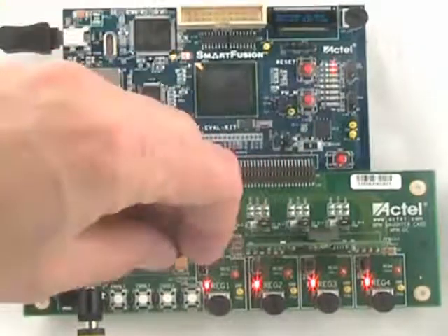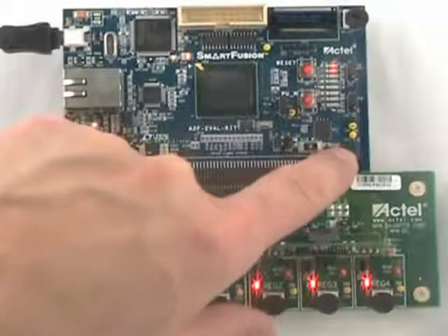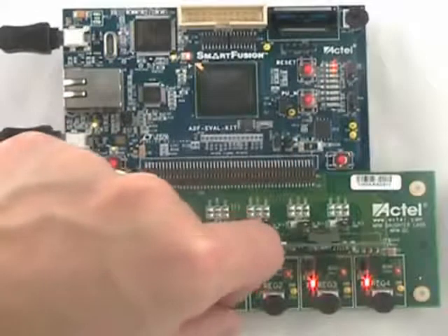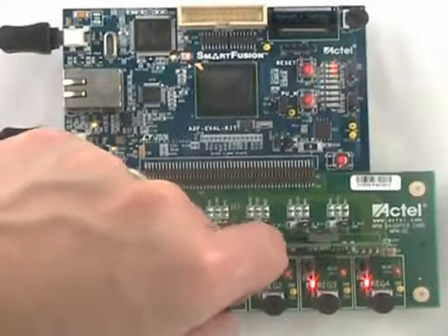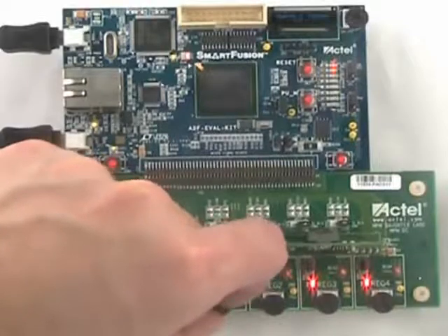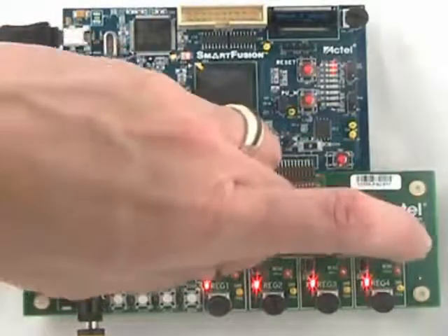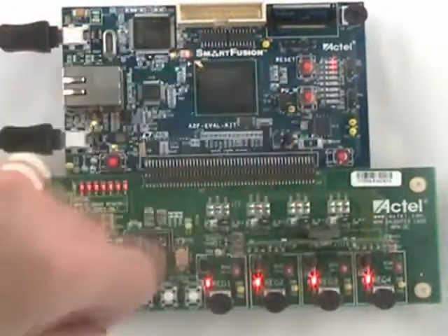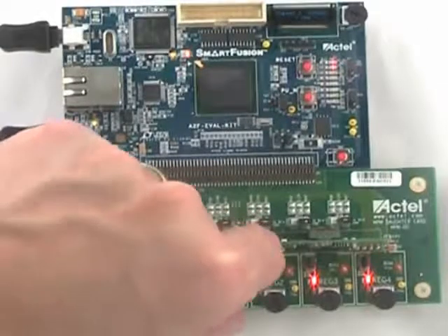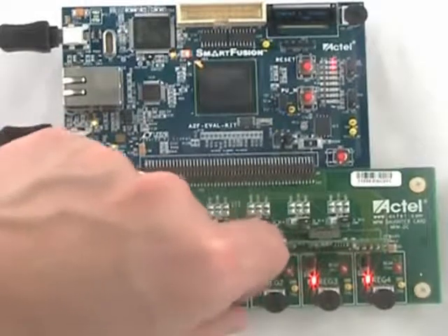Now if I change the tab, change the display here to show the output, and I rotate the potentiometer for regulator 1, you can see the settings changing up there on the OLED display through the various set points set in those thresholds. Now if I put the jumper on to re-enable trimming on rail 1 and turn the potentiometer up and down, you don't see any changes at all up there on the OLED. And in person, you could obviously see the values not changing as well.